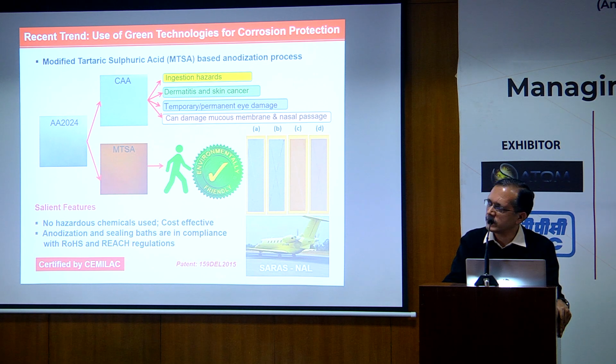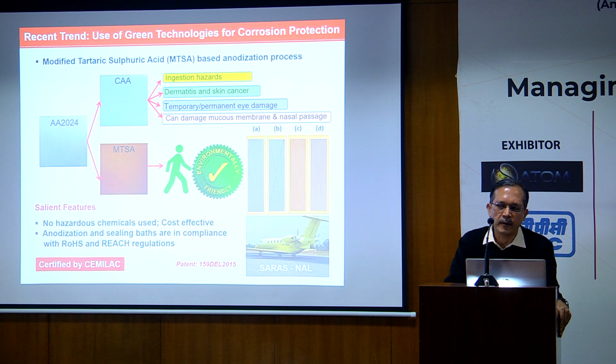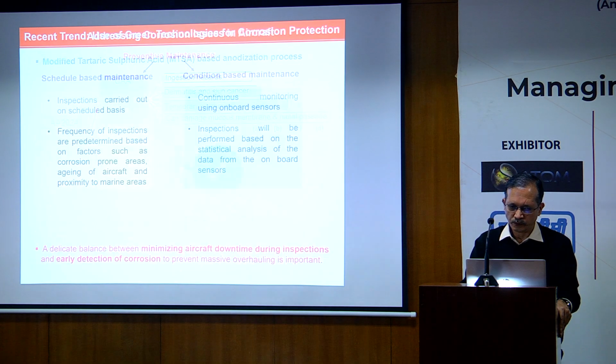One of the technologies which was developed and certified by CEMILAC is listed over here. Here we use the modified tartaric sulfuric acid anodization process in place of the conventional chromic acid anodization process, and it complies with the European regulations of REACH and RoHS environmental regulations, so it is a fully green technology.